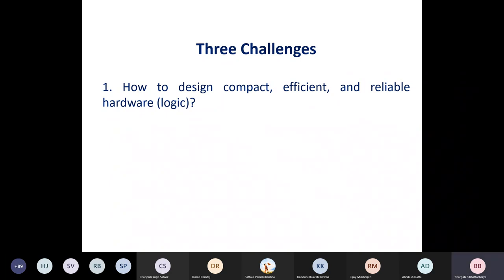Now just imagine this scenario that you have a small chip, a small processor whose area is very small, where so many transistors have been compacted, and each of them is pulsating with a high frequency, changing the state between 0 and 1, 1 to 0, and so on. Therefore, they will dissipate an enormous amount of heat, and the chip might burn out. So therefore, it has to be power efficient, it has to be energy efficient. At the same time, it has to be speed efficient. Okay, so there is a trade-off between delay and power.